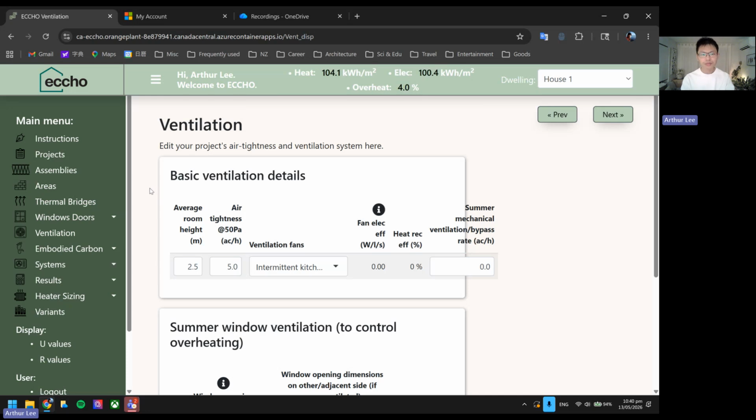the result page. So as we know, if we use the building code as the baseline, there is basically no requirement for mechanical ventilation other than the intermittent kitchen and bathroom fan only if people do decide to turn them on. So basically, in any building, I will always suggest and almost treat having a mechanical ventilation running 24/7 as non-negotiable. That's for two things, basically the health of the people and the health of the building itself.